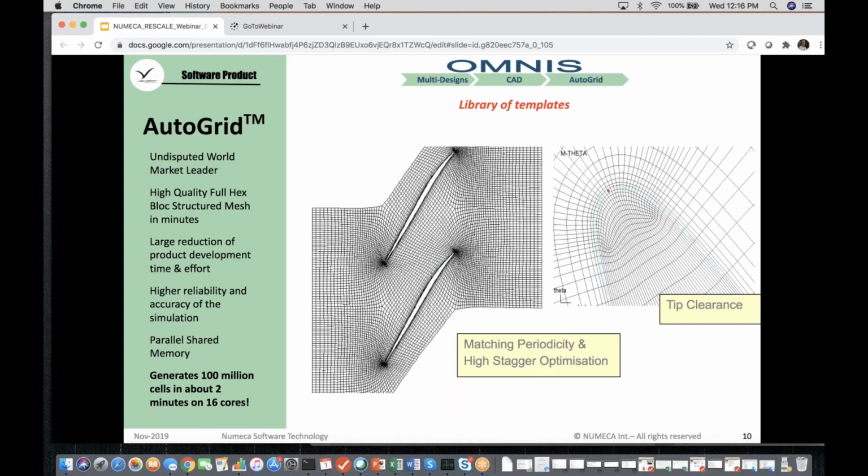And what's very important too is that you can use this same topology for successive blade designs, and you can change that shape quite significantly, and this template will still apply. So you can close your eyes and mesh this. And this is actually what people do with AutoGrid. They do close their eyes, and by that I mean execute in batch on the design cycle. You can execute meshes like this, and a mesh like this executes in a minute or two, depending on the size.